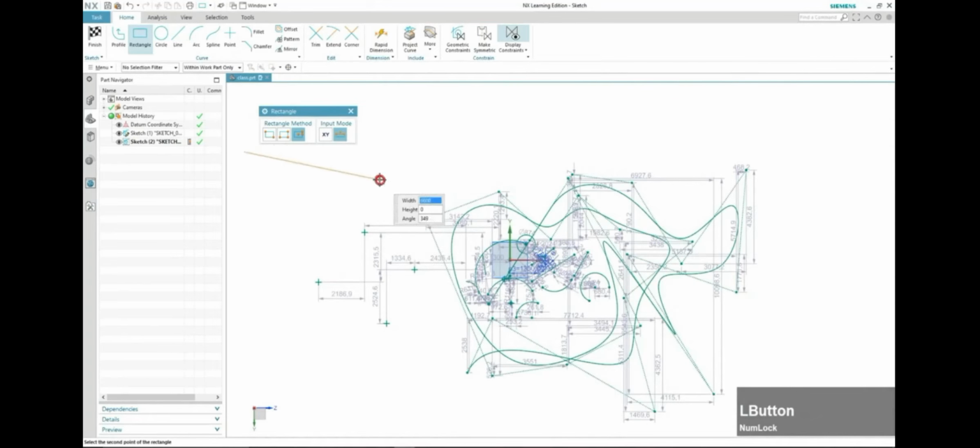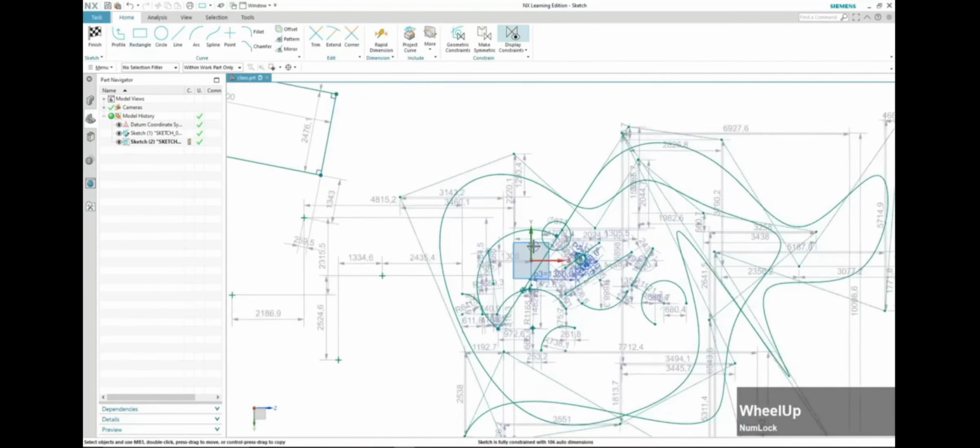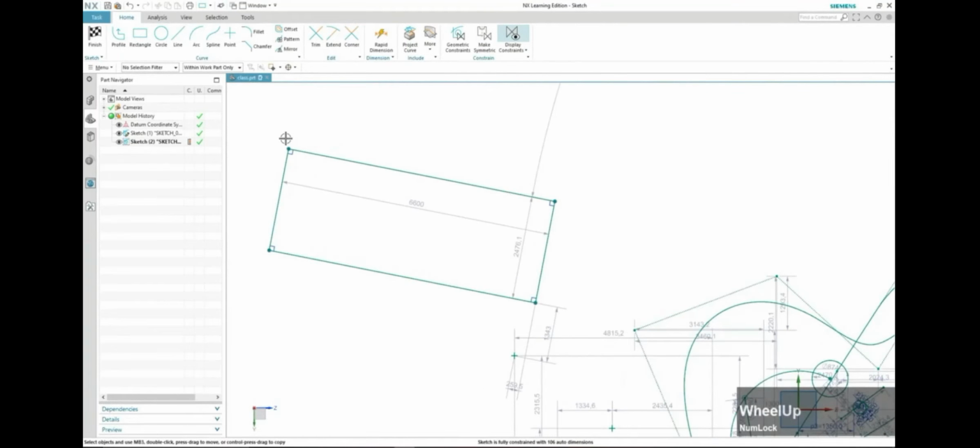As we can see, every component in practical condition does not have any sharp corner. Whichever component you can see with your eyes, maybe it would be of metal or plastic, it is not sharp usually, right? So in engineering, we have learned a term called stress concentration. Wherever there is a sharp corner, there is a chance of stress getting concentrated over here. So to avoid stress concentration and for smooth flow of stress, usually chamfers and fillets are used. Now we will look at chamfer and fillet.